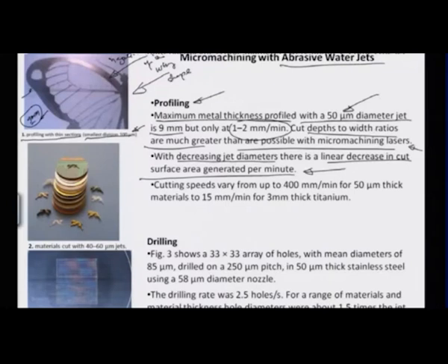On one side you have a thickness of 9 mm, on another side you have this teeny tiny feature here of not more than 100 microns. So you can think of the high aspect ratio. So this cannot be easily obtained otherwise on any other machining process except this abrasive water jet. So that's the power of this process in being able to micro size the parts.